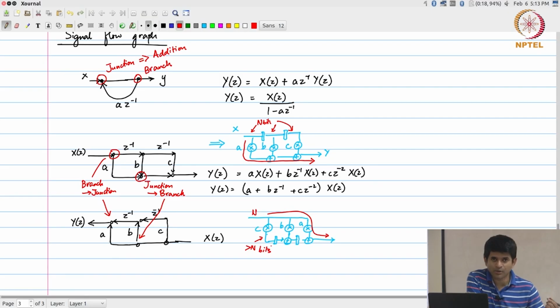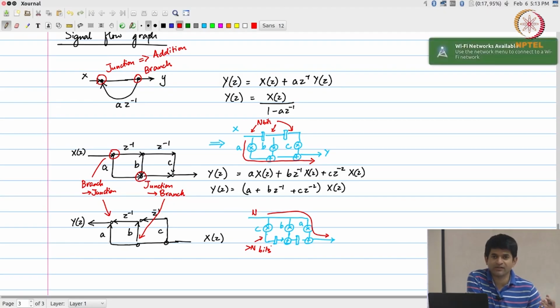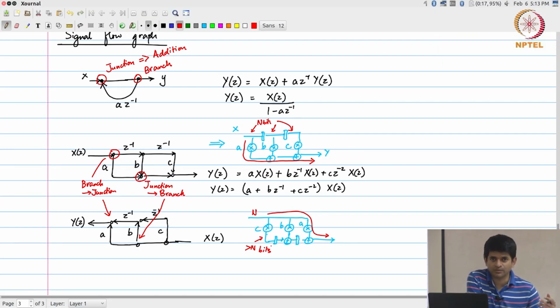Okay, that's one problem. I may be able to get around that by saying I'll use a fixed point representation. Since I know that it's fixed point anyway, what I'm going to do at the end of the day is multiply two, let's say 8.8 numbers, and round the result off also to an 8.8 value. If I do something of that sort, I may be able to get around this shifting problem. Nevertheless, it is something that I'll have to deal with.